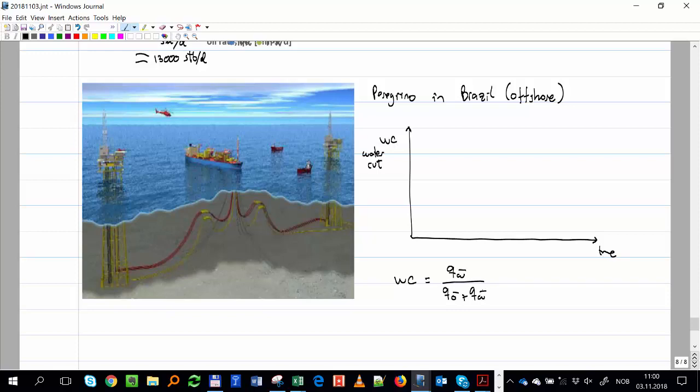Okay, that's how we define water cut, and usually in the life of the well it is 0 or a very low value, but it starts increasing, and you can get up to numbers. In normal fields it is something like maybe 70, if I multiply here by 100, okay, around 70%. But in this field in Colombia, it was like 90%.